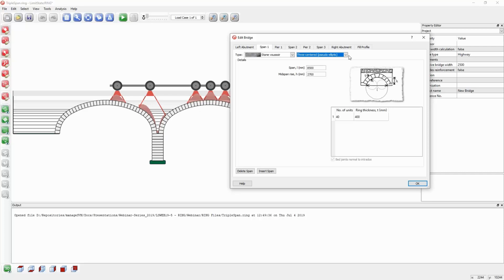And that's because it's the shape of the arch barrel and other masonry elements in relation to the applied load that governs stability. So if you get that shape wrong, then all your outcomes from your analyses are likely to be inaccurate, or not particularly accurate, depending on how far away you are from the true shape.